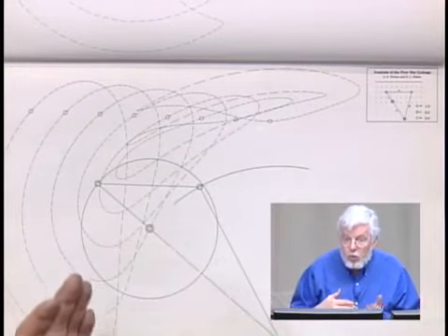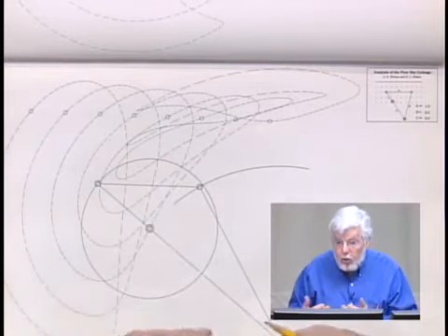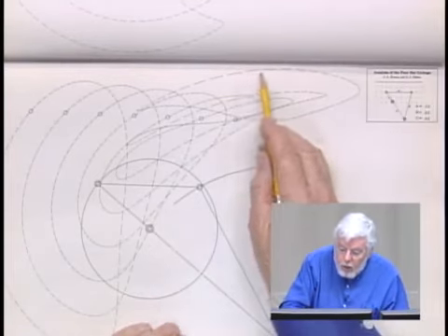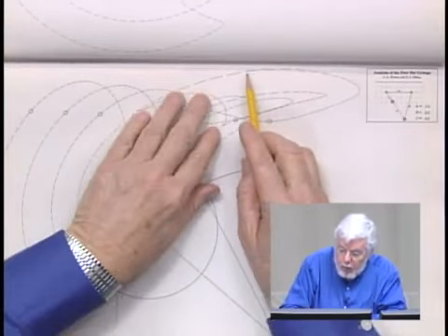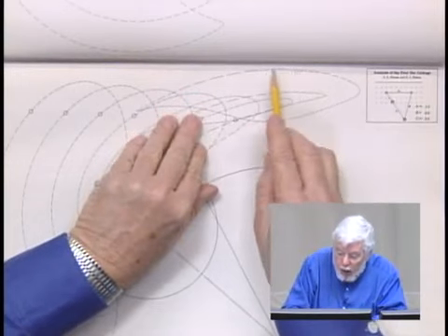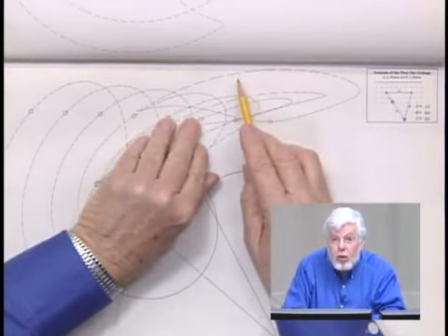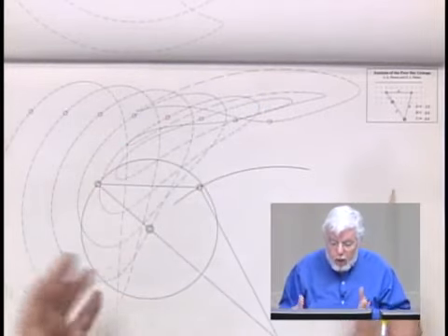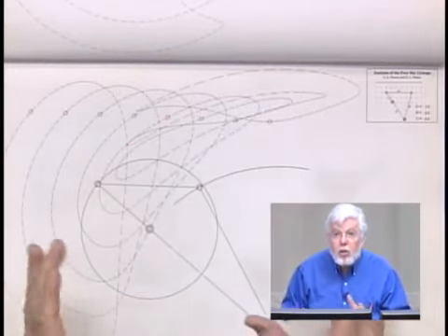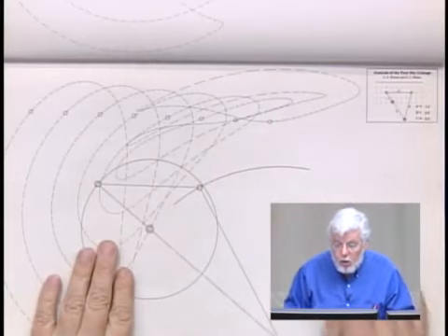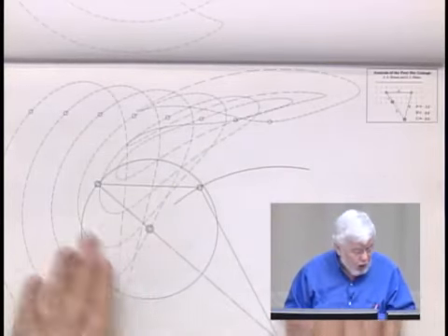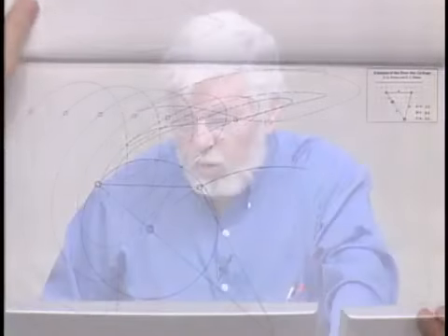I can actually impute some crude acceleration information, because as the velocities, as indicated by the lengths of these dashes, are changing rapidly, that indicates I have high accelerations. I can't get any real acceleration numbers out of that that are worth anything. But I get a very good, holistic, intuitive feel for the way that curve is going to behave when I drive it with a constant speed crank. Okay, enough of that. Let's move now to the program.